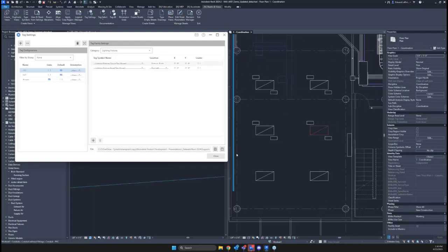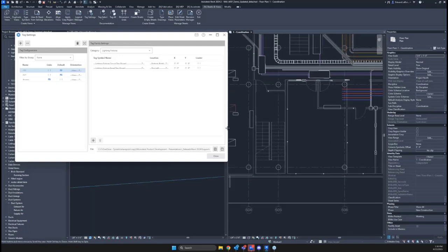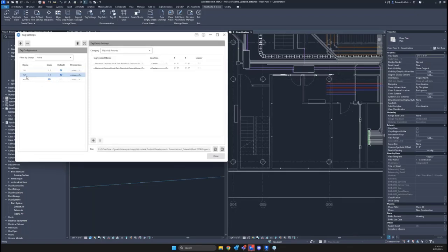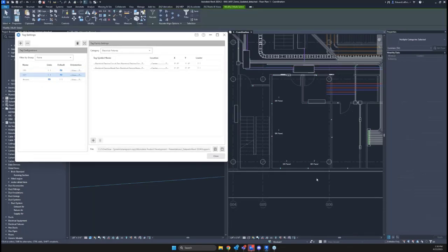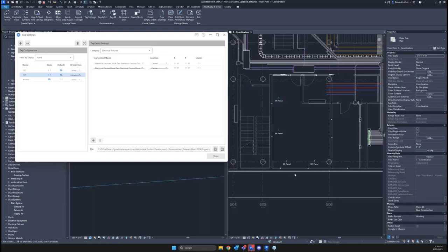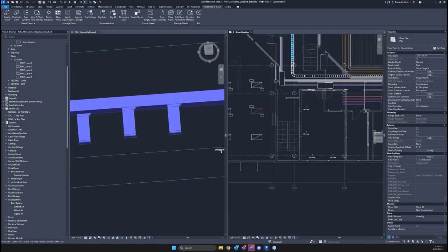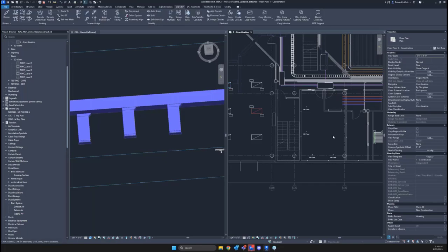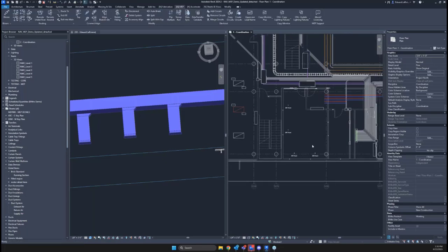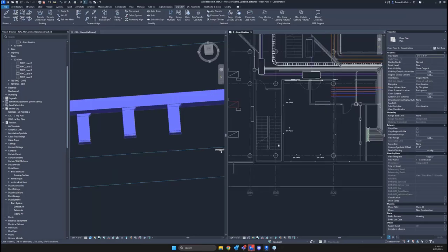So these tagging tools are incredibly quick ways to jump in and start tagging elements. If we jump down to fixture tags, we'll see the same process here, giving me all those circuit information for my electrical fixtures. Now I'm going to close out of this window, but we're going to still use these tag tools, leveraging some of the other commands as we go. So I've got some elements tagged. That's great. Why don't we jump up to MEP now and see some of these circuiting tools we have access to. So the first three here, these are just to help with menu diving.